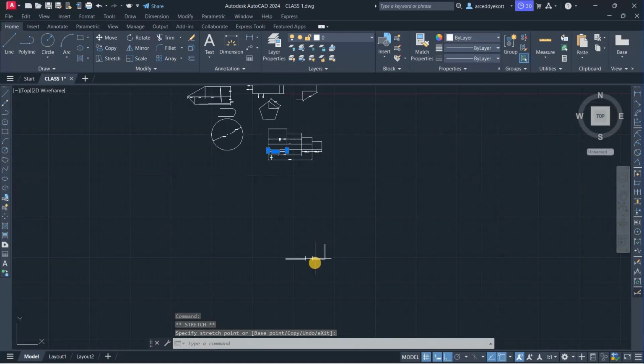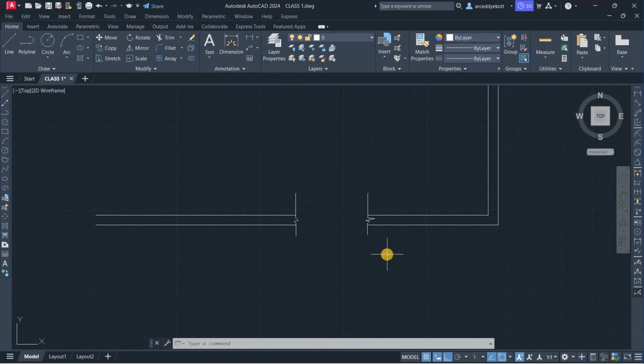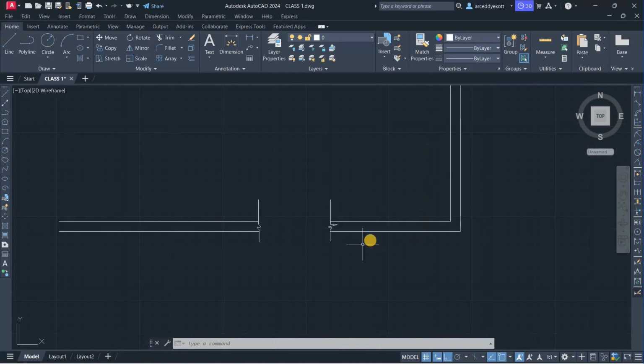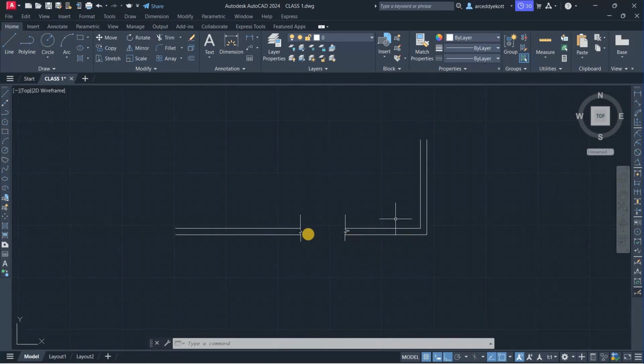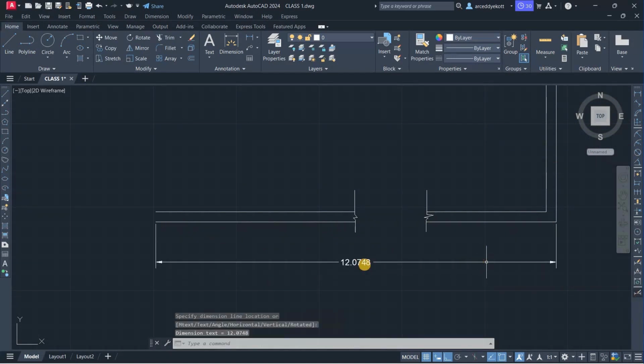Of course, this is exactly an example of a case where it may require a jogged linear, where you have two walls in a building plan continuing, but in your own drawing you don't want to draw it fully to scale. You just want to draw parts, and then write the full length of the dimension that it will be constructed on site. So you can have a linear dimension of a wall here from this to this.